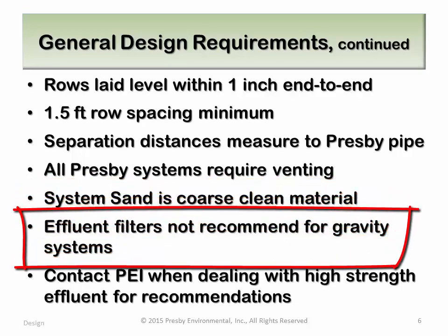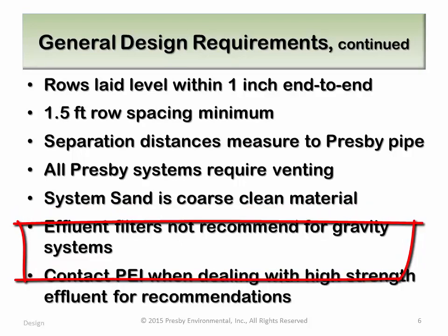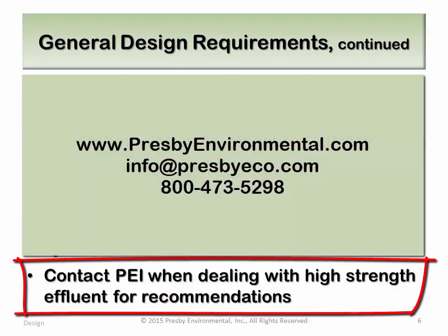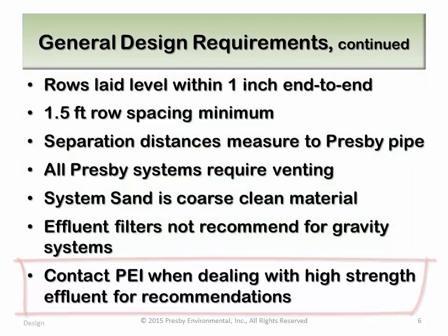Effluent filters are popular, however, they are not needed or recommended for use with Presby gravity systems. They can reduce airflow through the field. When dealing with high-strength effluent, contact Presby Environmental's technical support for design recommendations. You'll see a definition for what constitutes high-strength effluent in the manual.